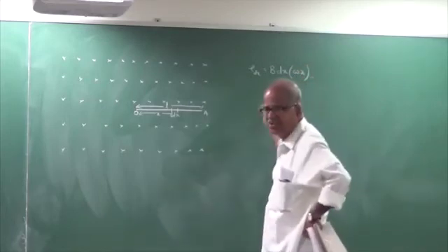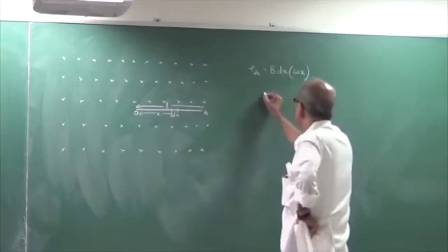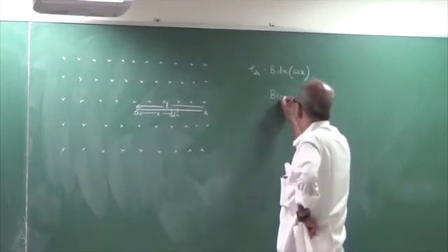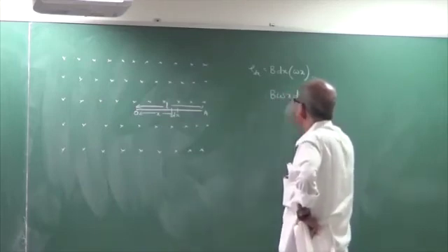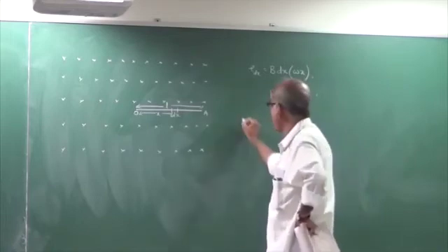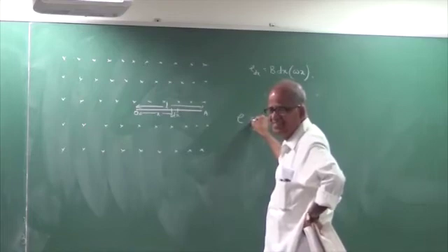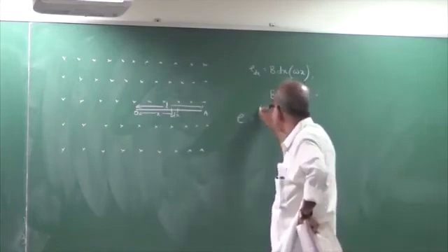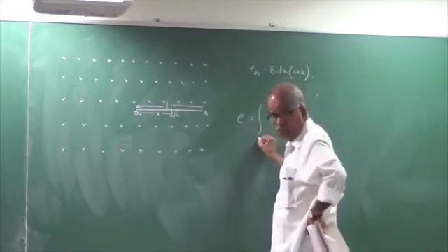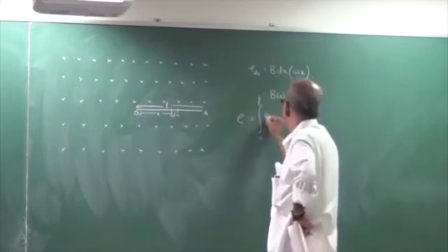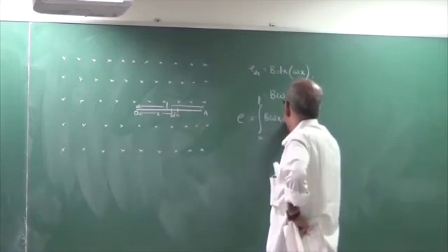It's not a linear motion there, it's rotatory motion. So this is B omega x dx. So what is the total EMF induced in the entire rod? Integrate this from 0 to L. What is the answer?